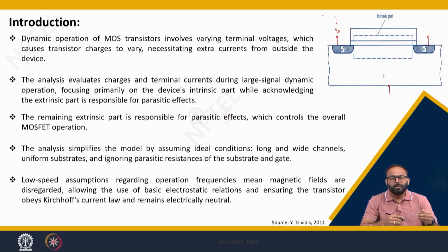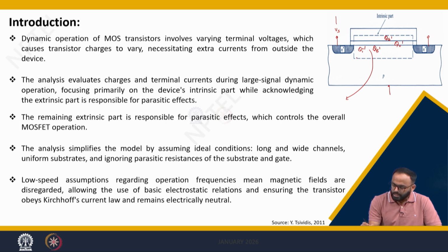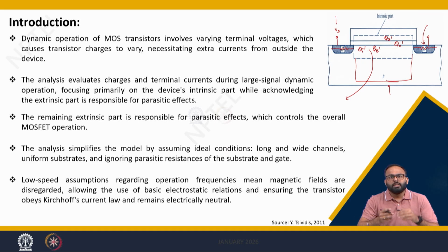The analysis will evaluate the charges and the terminal currents during large signal dynamic operation, focusing primarily on the intrinsic part of the devices. Here, intrinsic part of the devices means it is related to inversion charge, bulk charge, gate charge and oxide charge, as well as some amount of substrate electrostatics. At this stage, we are ignoring the extrinsic part of the MOSFET, which, yes, obviously will control the overall MOSFET operation. So, we will see the influence of these external effects in later modules.